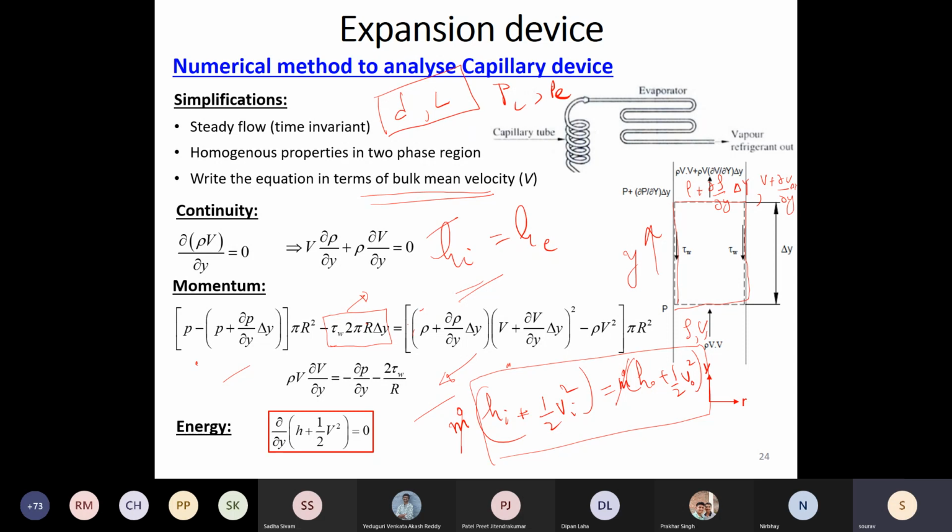Okay, so what is specified is, I need a capillary tube for my refrigerator where the refrigerator evaporator temperature would be -30. The condensing temperature, let's say, is at 40 degree. This will be specified. What is the mass flow rate required at this condition? That also needs to be specified. So m dot needs to be specified, because that determines the capacity of the system. So this I would give to you, and now you have to come up with the appropriate diameter and the length of the capillary tube that I will go and buy and attach it.